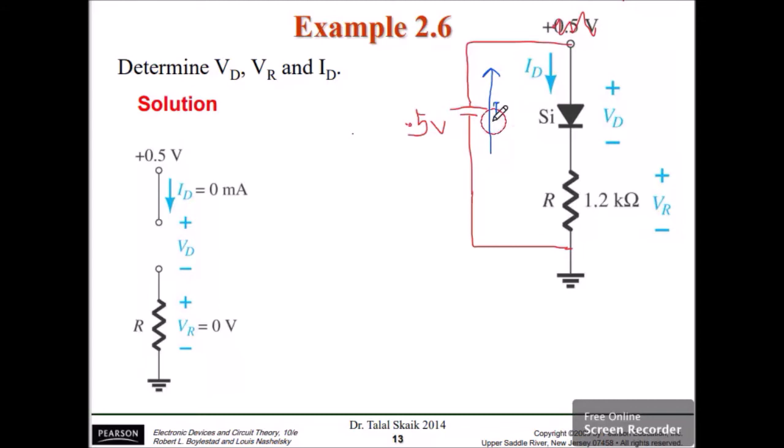This I is also the ID, right? Because it's still the same. Okay, so this is our I, this is our ID. Will our diode let it through? Yes, because it's the same direction. So, check. Our diode is on. It goes to the resistor and then goes back, so we have a closed circuit. There's no open, so we probably have a value.